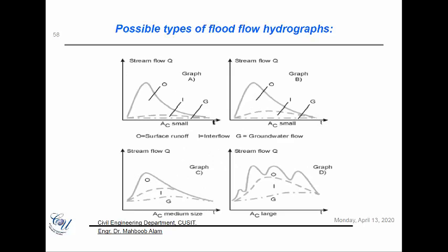Also, as we looked at the earlier graphs where the time series showed us what kind of catchment that is, in terms of whether it's a perennial river or a river which flows for just a few months and then is dry, you can also have an idea of the size of a catchment by just looking at the hydrograph.